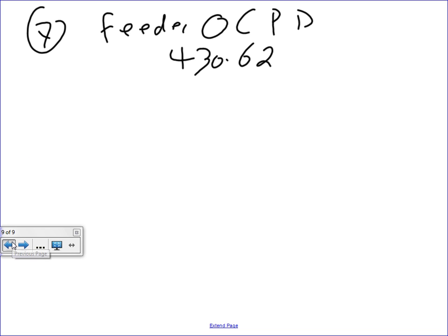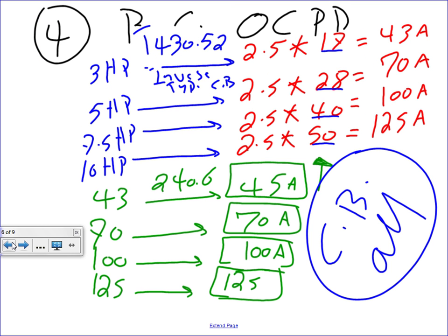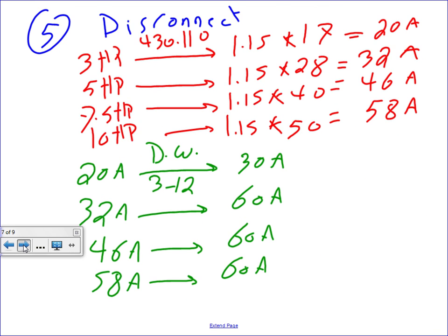So what's my overcurrent protection device for the system? We're going to go all the way to the overcurrent protection device, right here. So, Chris, what's the largest overcurrent protection device in the whole system here? 125. Okay? Take the largest. I made them all inverse here. If they were a mixture, you take the largest regardless. So the largest overcurrent protection device. Do you guys agree with me? 125 is larger than all these circuit breakers? Okay, so take this 125 all the way.